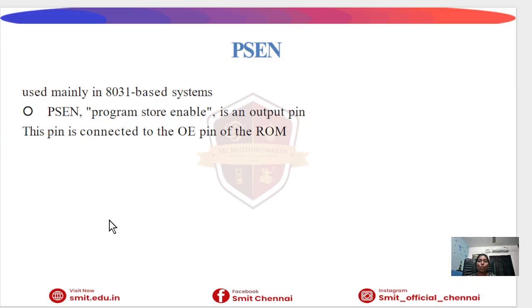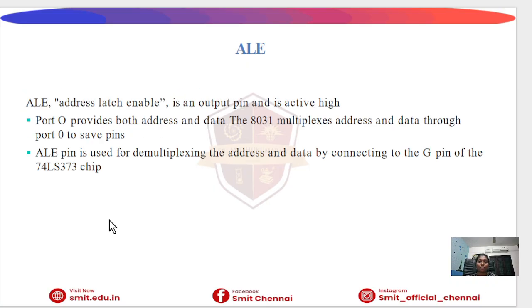When the microcontroller wants to read a program instruction from the external ROM, PSEN becomes active. Only if PSEN becomes active can we read the program from the external ROM.